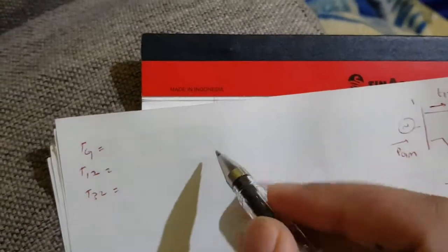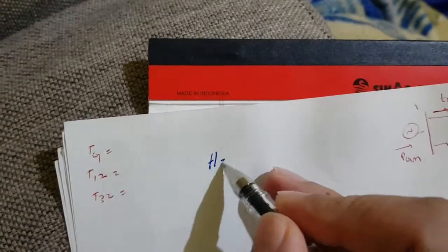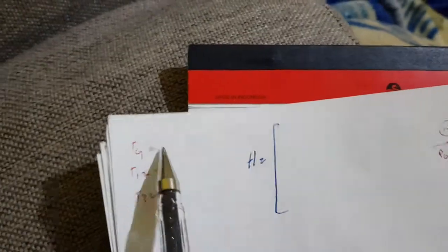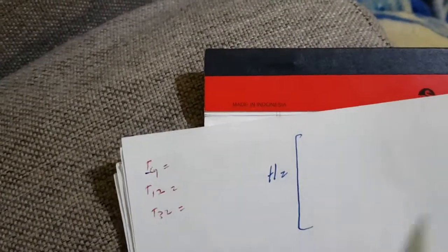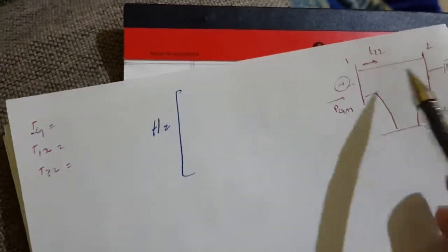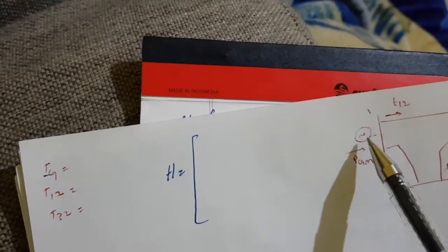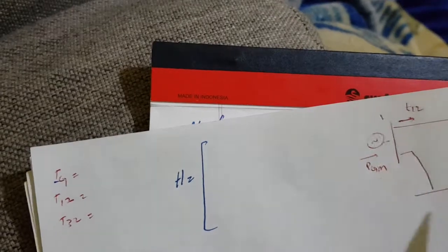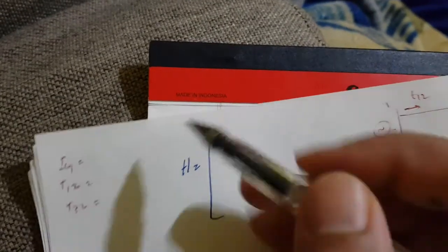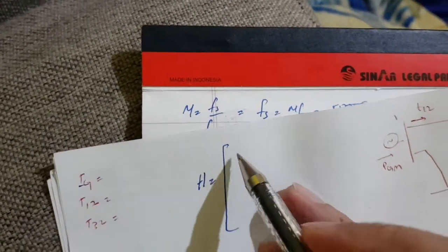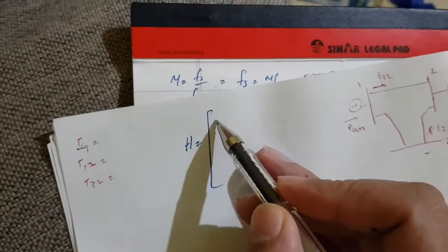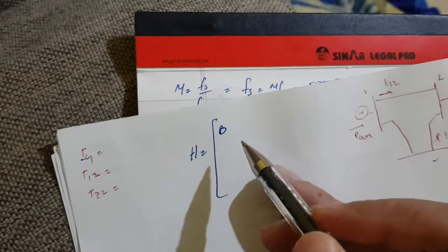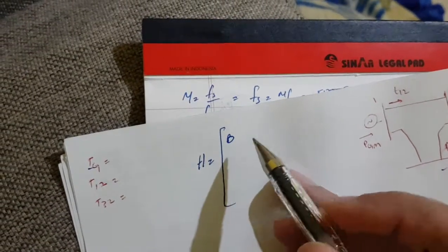Now we have to find our H. There are three buses. Now the first point is TG, I mean the generator. You can see that the generator is feeding from bus bar 1 to 2 and 1 to 3. So we will take the susceptance B. B is not bus bar, B is susceptance, or 1 over X. It's the inverse of reactance.